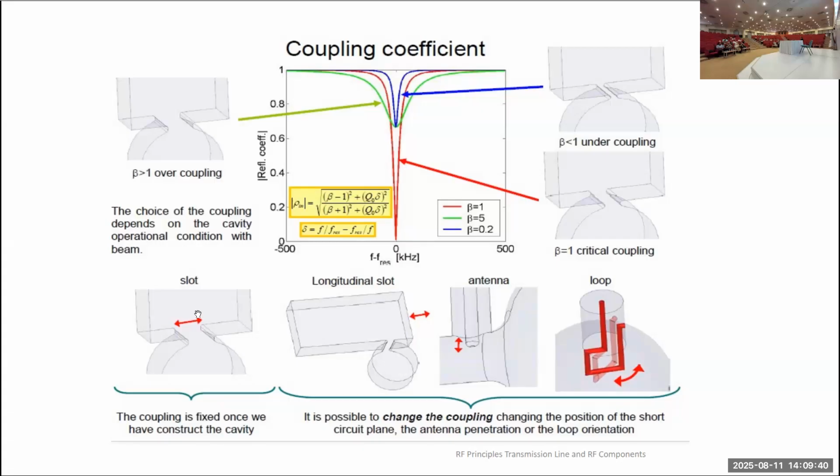Is it also possible to use impedance matching stubs? Yes. Whenever we design, we use impedance matching. But when the frequency is changed, the cavity is not resonant to the frequency, and RF power is changed inside the accelerating structure, and that change in RF also changes the quality of the beam which is being accelerated by this RF field.